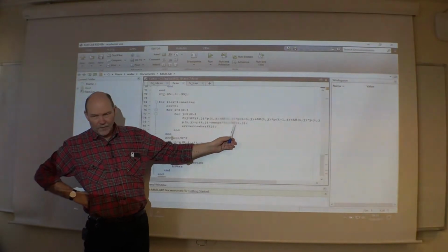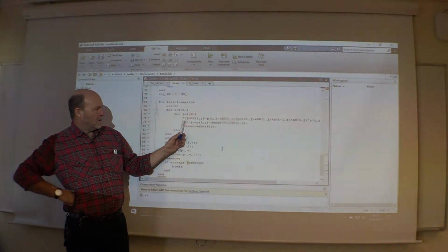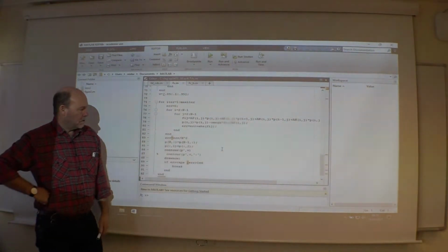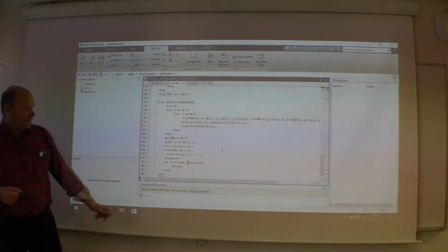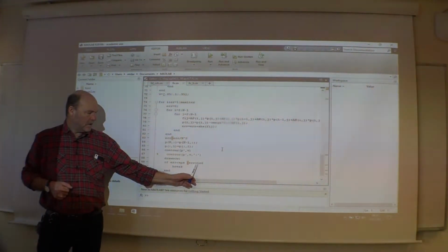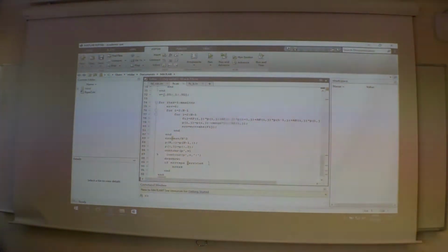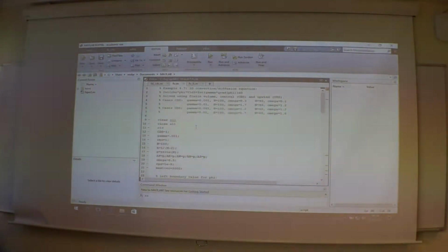You divide by the derivative at the center point you're looking at, and that should now be the coefficient AP. And then I calculate the residual as well. So it will stop if we have an overall residual smaller than a given number here. Also it stops if the residual becomes too big, then it has exploded. So let's try this one.